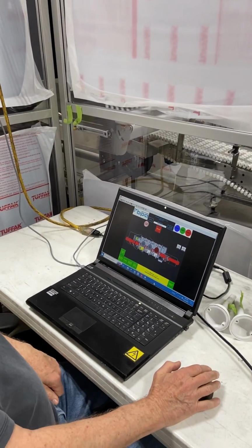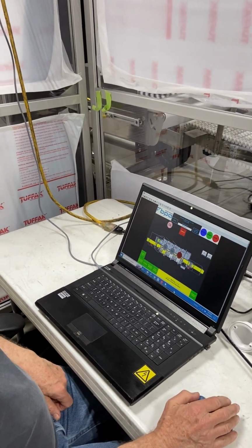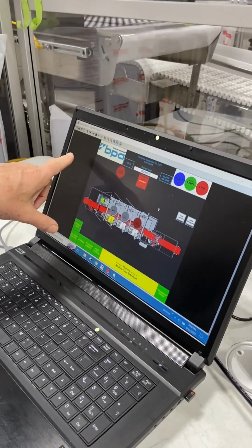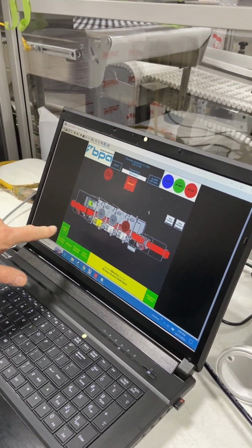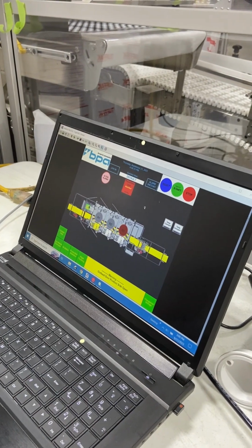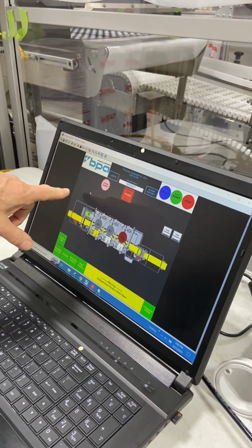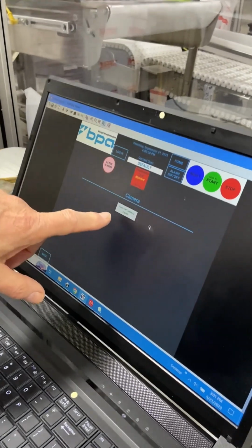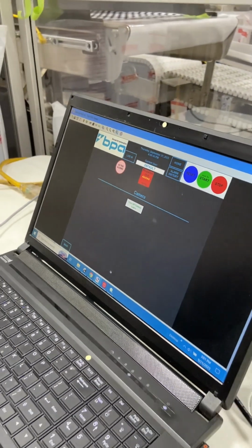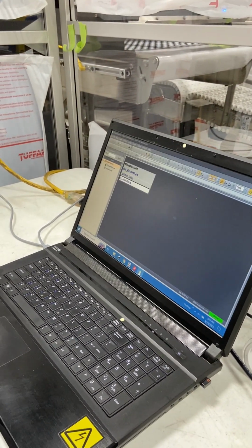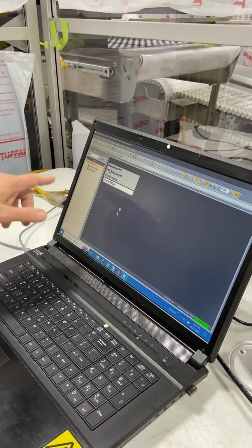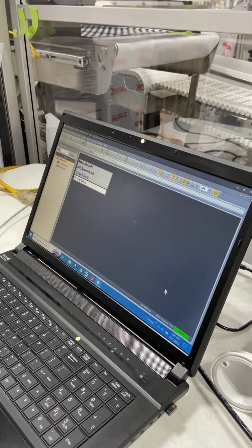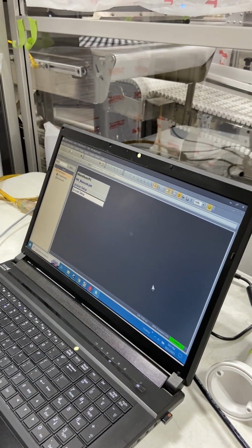Okay, here's the software setup. We're going to assume that you have TightVNC on your computer. So right now on my computer screen, I have access through TightVNC. The first thing you want to do is come to the main HMI page, click the camera page, and then turn on the camera lights. Just one button there. You're also going to need to have Insight Explorer on your PC. It's version 6.5, so be sure you have that available and installed on your computer.